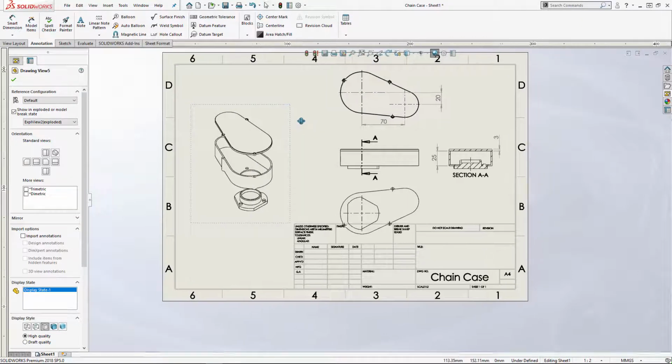So the next thing I'm going to address is the angle of viewing of this view. It's not really suitable for us because it's doing what I said you shouldn't do, where visually these components are overlapping each other. So that's not good practice for the reasons that we've already talked about. So what I want to do is rotate my viewing angle. The way that you do that is you select the view and then click on that icon there. It's like a sheet with an arrow coming out of the sheet.